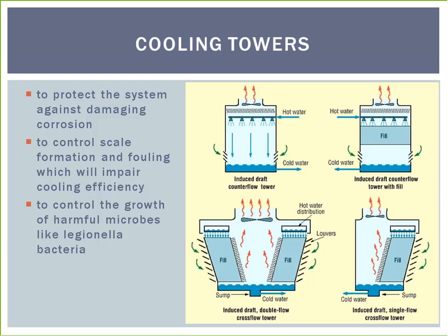The purpose of a cooling tower water treatment program is essentially threefold: to protect the system against damaging corrosion, to control scale formation and fouling, which will impair cooling efficiency, and to control the growth of harmful microbes like Legionella bacteria.